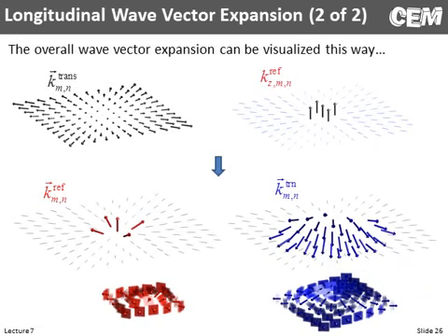So here's a better visualization of it. The upper left, we have the transverse components. On the right, we have what the Z component of the reflected wave vectors look like. Now, if we were to tie all this together, this would be a way to visualize the reflected modes. The center few are real propagating waves. The rest of these higher order diffracted modes are cut off.